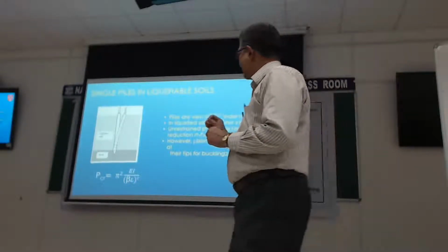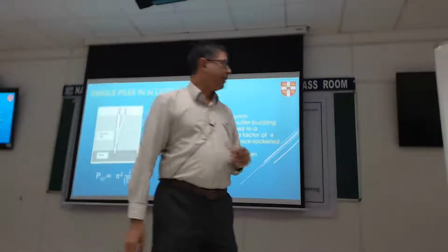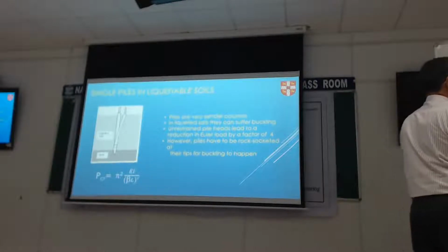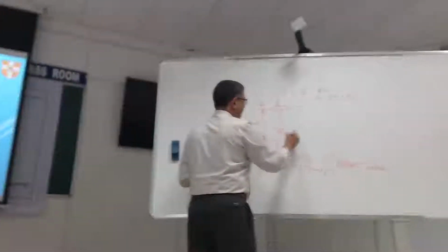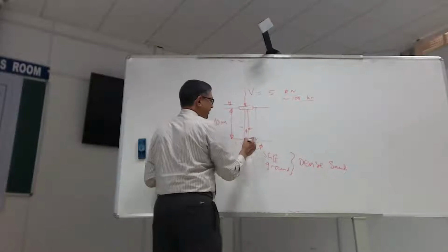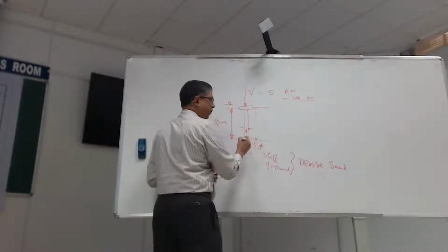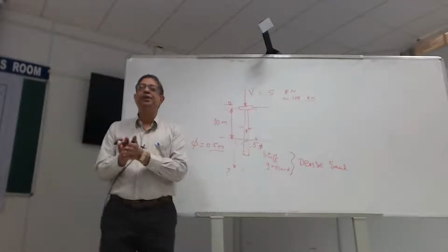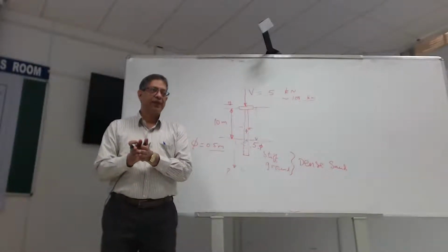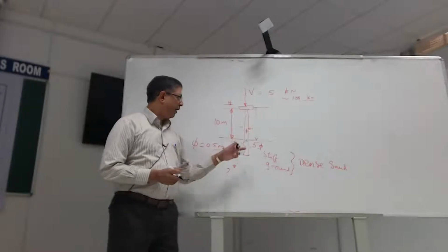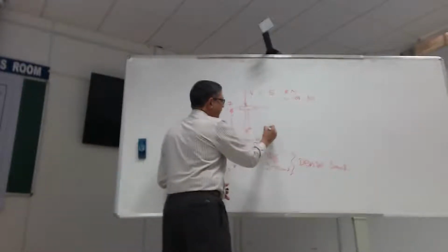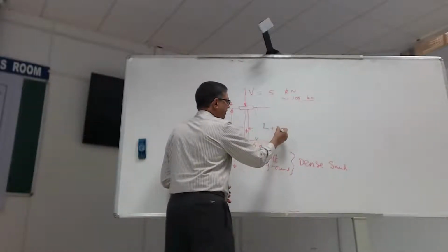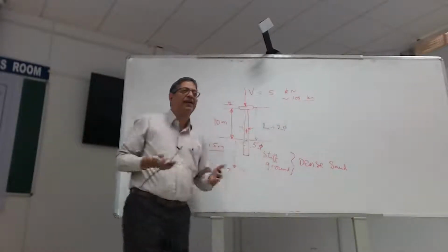The other important thing is L. Do I take L to be this length, if you imagine the hinge to form there, or maybe a little bit deeper? That's a decision you need to make. It will be some function of L, or L plus maybe 2D, 2 diameters, or something like that.